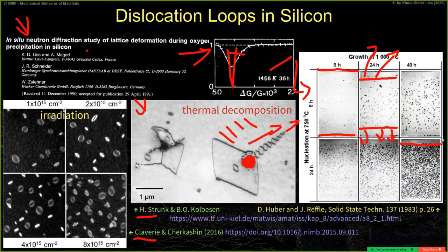So you see there are sharp layers where we have precipitates of silicon oxide here, and layers which are depleted of oxygen without precipitates. And that's good, because electronics we build onto the surface. The electronics we build on top of this depleted layer, pure silicon layer. Then we have a lot of strain fields due to the dislocation loops from these precipitates in the bulk.